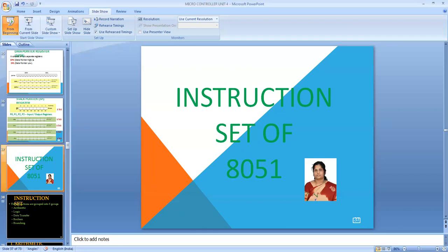Okay. So whatever the source and the destination, the AND operation will be performed based on the truth table of the AND operation, and the result will be stored in the destination. Similarly, we can perform the OR operation. The OR operation is indicated by ORL. L stands for logical operation.